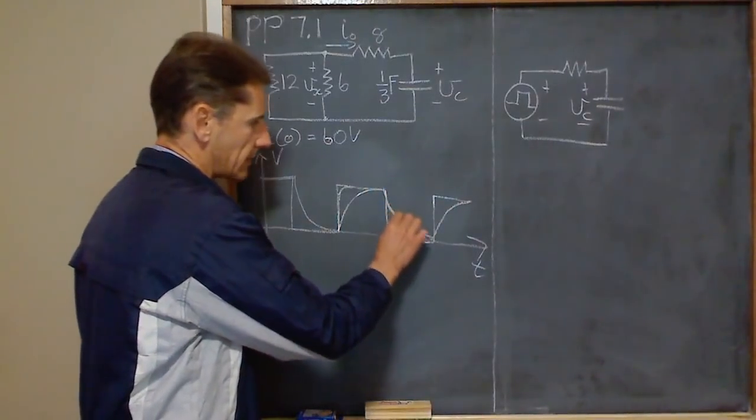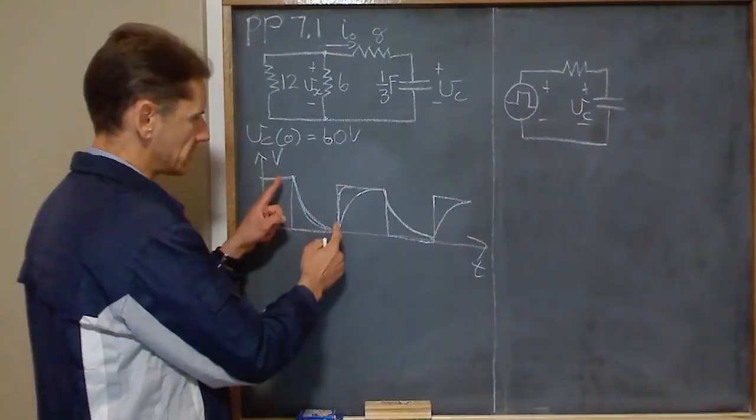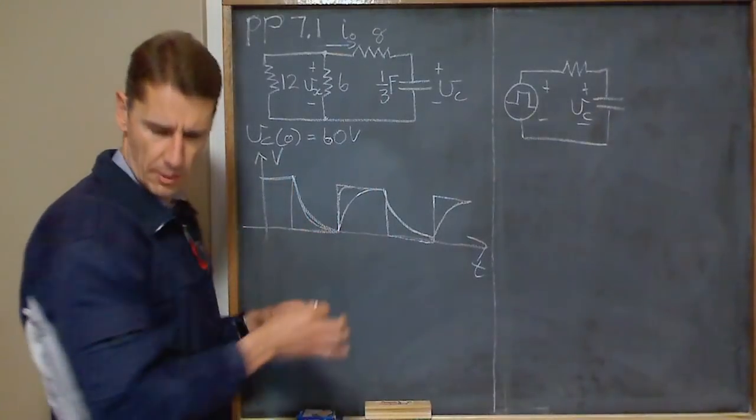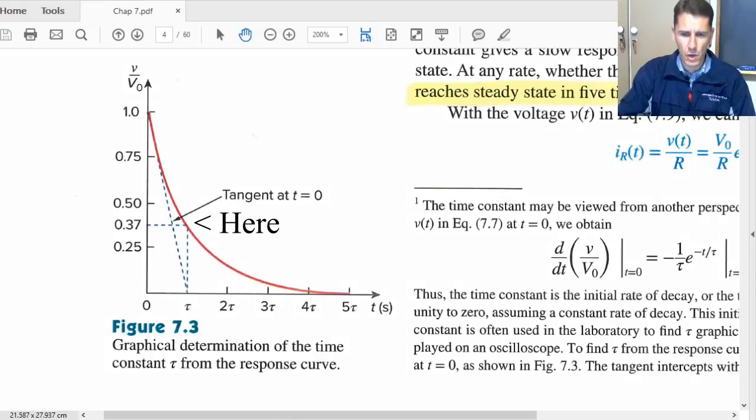You actually want it to look something like that. So that is how we're going to get that discharge response, which the textbook picture that we're discussing now is only looking at that little section. So let's just go back to the textbook. So back in the textbook, you've got that RC circuit discharging. And now we're looking at the three ways that you can calculate the time constant. The best way to do it is to take that peak value there where it started, you measure that, and you times that by 0.368. You take that measurement there and you draw a line to your graph and downwards, and then you get your tau value.